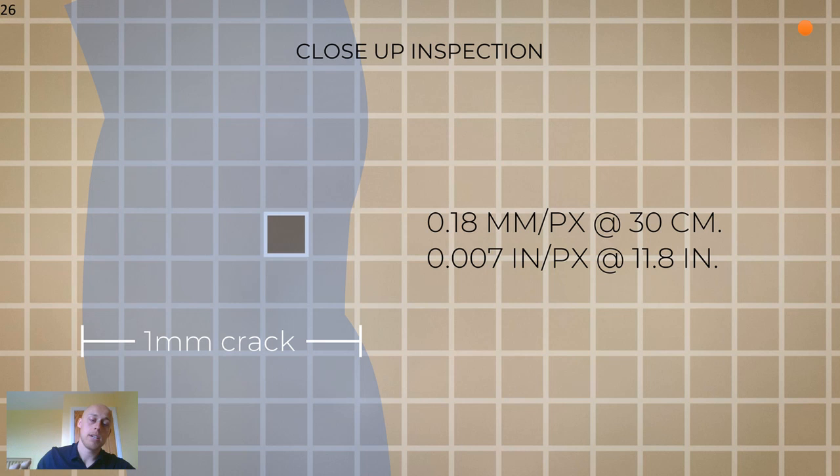Additionally, and this is where the safety side comes in, you can fly closer to the objects, and that will give you more megapixels for that size, but you are having to fly a lot lower. If you're doing a site survey or an inspection of a building, you want to fly at a decent height so you can do it quicker and capture more ground and more data without having to fly lower. That matters for safety: if a huge gust of wind comes in, or something goes wrong, or you lose connection to the drone, you're not going to be caught out. You want to fly at a decent height, fly with line of sight, and having a camera which can do that is really going to be key.